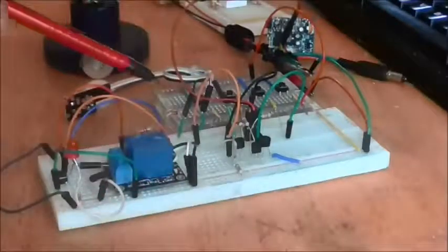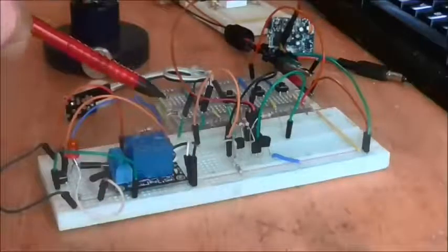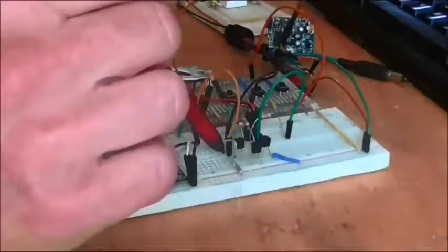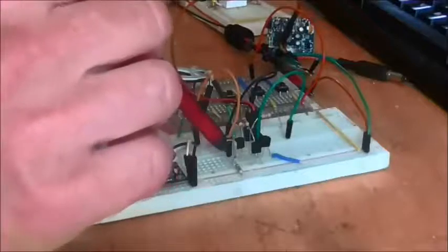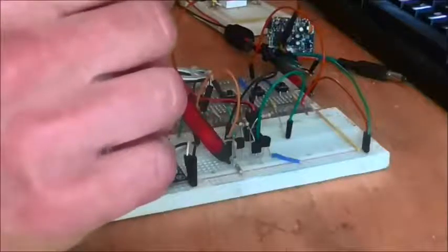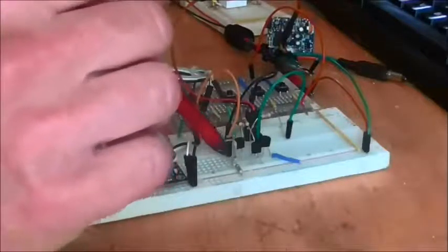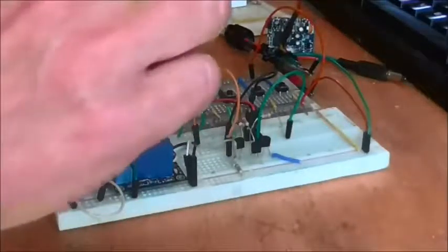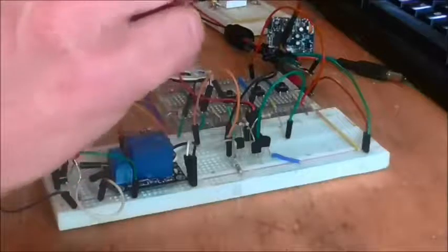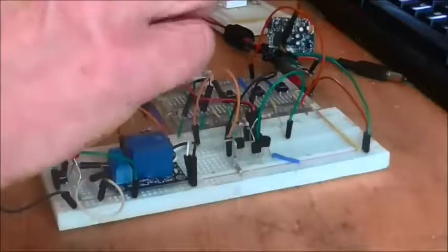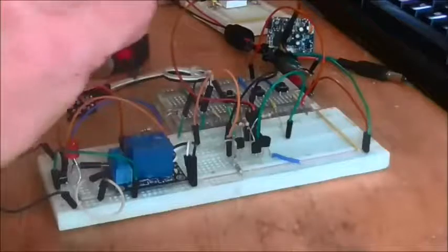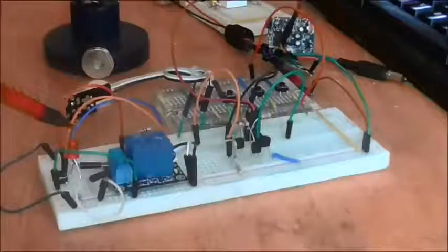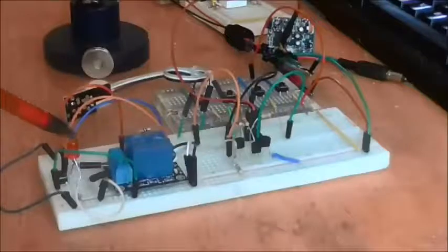I have here a small signal diode which sends through this orange wire back to the signal wire of the relay, which is placed at the end of the gate there. It also comes down here through a 220 ohm resistor to connect with this LED, which is serving as a visual indicator for the output at the moment.